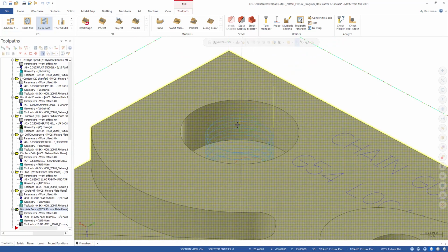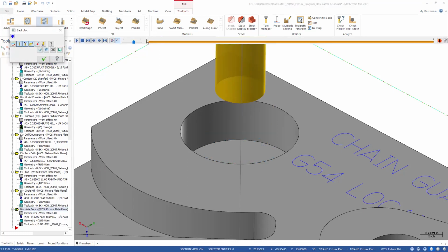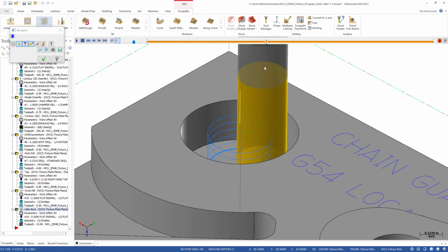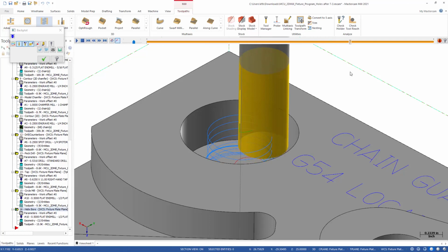So now let's look at this toolpath compared to the other one. The circle mill looked like that. The helix bore has additional helix motion. So we rough going down. We work its way to the outside. And then we finish coming up.